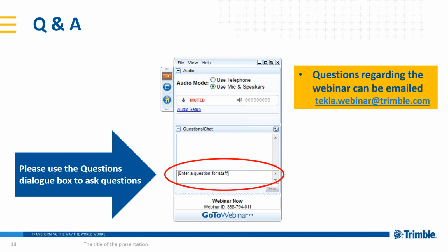First of all, the Unitechnik file format itself can include information about only one cast unit. And that's why every cast unit has to have a different file. But don't worry, with Tekla Structures it's not a problem, because you can export the entire model or only selected elements in one go, so you don't have to do it separately.